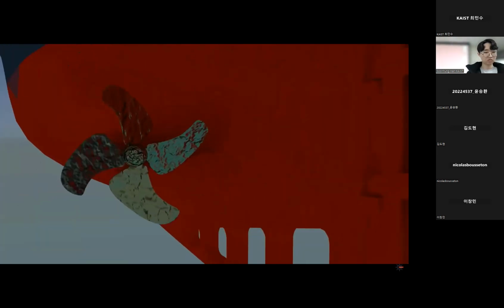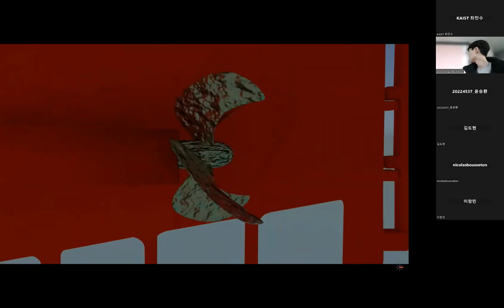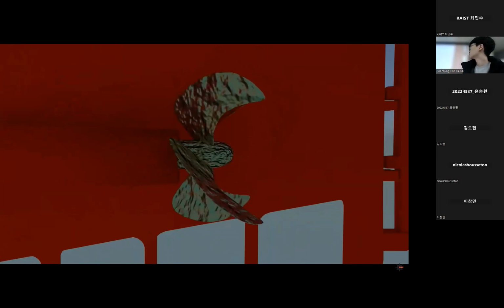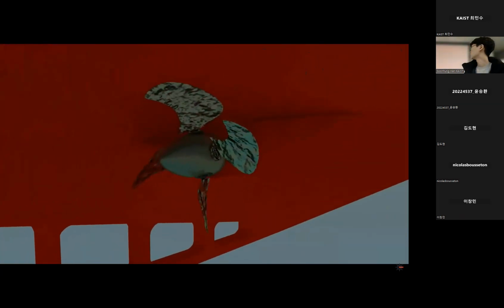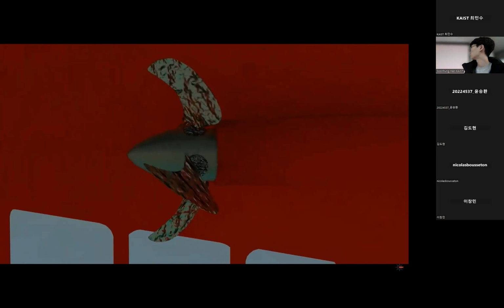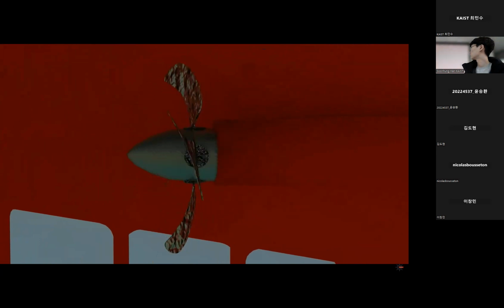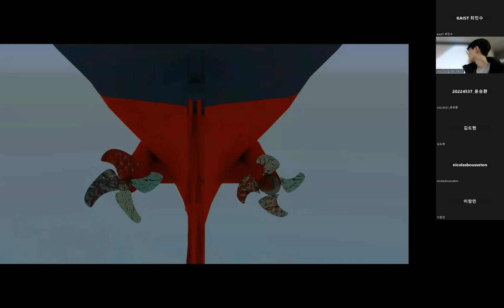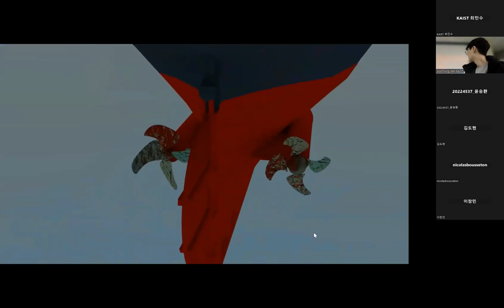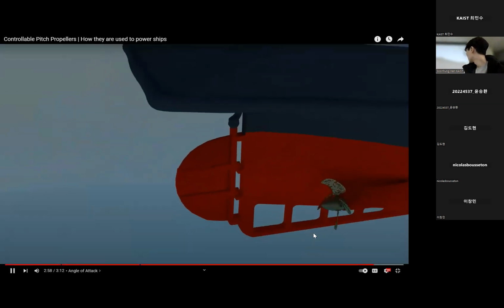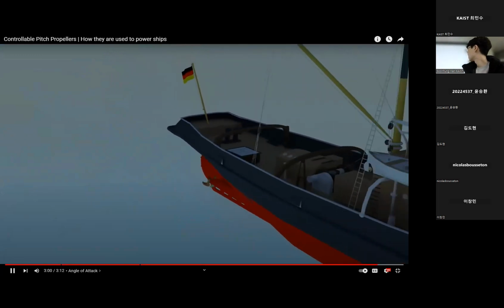Fixed pitch propellers, on the other hand, don't suffer quite as badly, as they are effectively always at their maximum pitch setting. The main takeaway point is that a controllable pitch propeller is constantly spinning. It's constantly generating a bit of water flow at the stern of the vessel. When handling a vessel at slow speed, that's enough to actually start a turn and throw you out of position. We call this effect transverse thrust, or propeller walk, but that is a topic for another video.